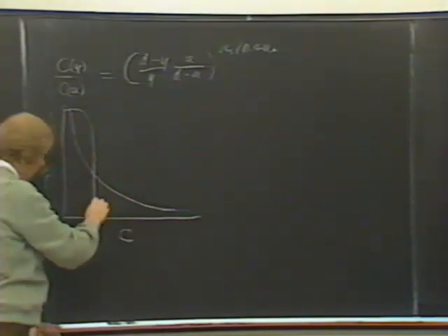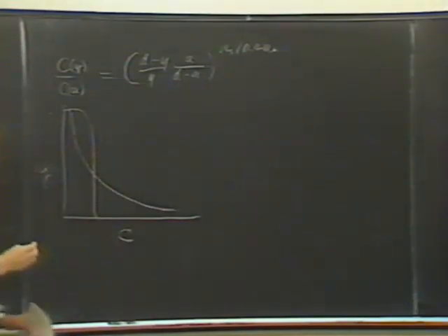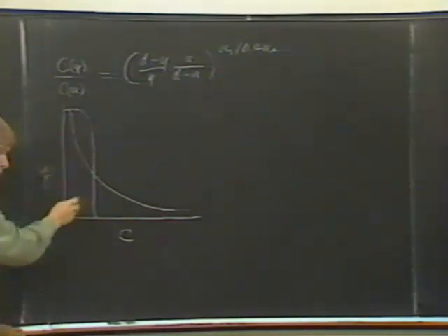In our case, the settling velocities are so low that we have this kind of a situation. Concentrations are virtually constant from top to bottom in the flume. Now that's not true in every case in estuaries, and I'll describe circumstances where that isn't true when we get into dealing with estuarial systems. But because the concentration profile is virtually constant, this is reasonably representative of flow in an open channel.